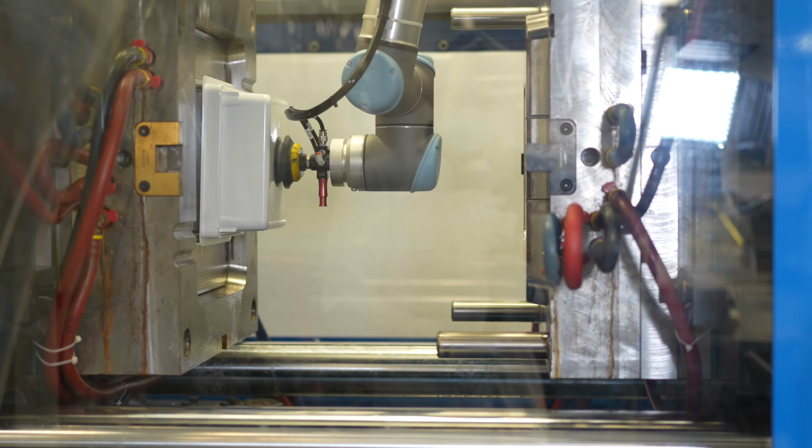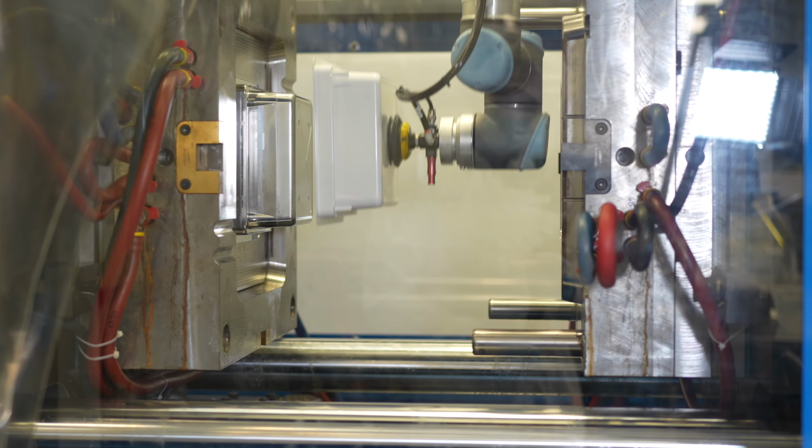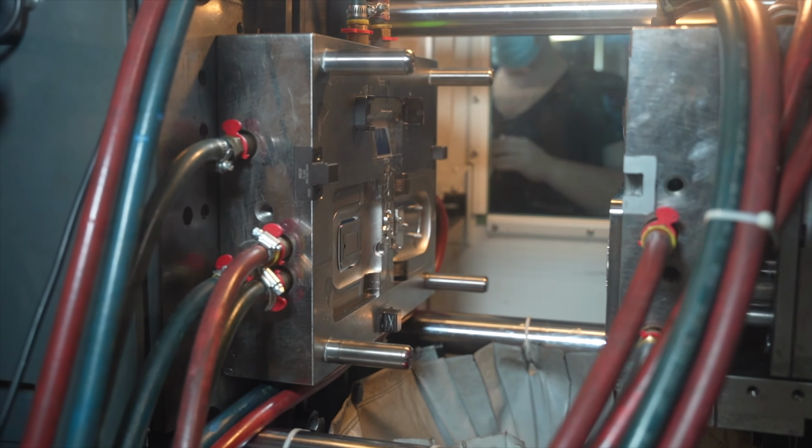So the best way to eliminate flash is by adjusting the injection molding process. First, we check the amount of pressure being used to press the two halves of the mold together, which is typically measured in tonnage. If not enough force is being applied to each half of the mold, then the melted plastic can more easily find its way outside of the mold cavity. Increasing this clamping force may be the easiest way to eliminate flash, but sometimes the material is too fluid, meaning that the melt or mold temperature can be lowered to improve the material flow.